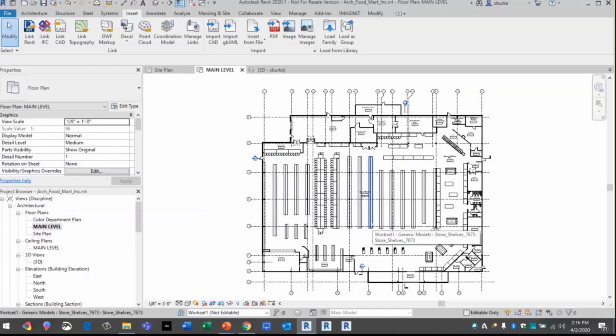So again, it's actually super simple to work on the cloud. And there are other tools inside of BIM 360 Design that have a much more controlled process when it comes to sharing files with others. Right now, what we're showing you in this example is the live linking model. Another way is to use something called swim lanes and distribution packages, where you only release certain models to individuals. It's a little bit more of a complicated process, but very powerful. Maybe I'll show a little bit of that later. But what I really want to talk about here is just the basic live linking.